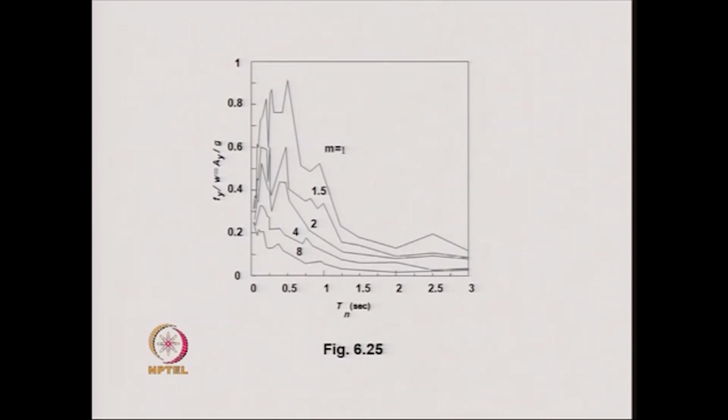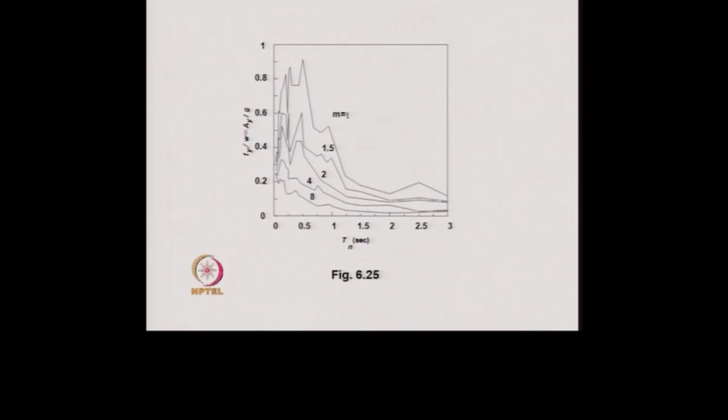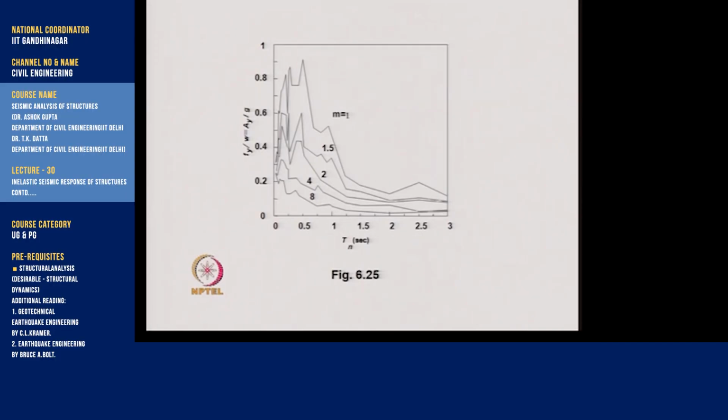Apart from that, the inelastic response spectrum can also be used for finding out the performance point for performance based design, in which a pushover curve, that is the curve of spectral acceleration versus the displacement, is plotted for a pushover analysis, and the intersection point with the inelastic response spectrum for a given ductility gives the performance point.